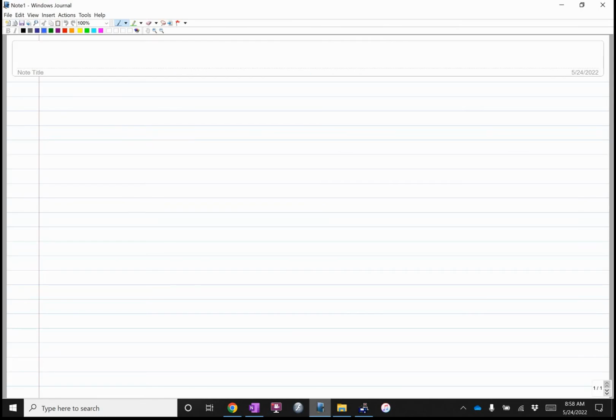So the amp hour unit, I'll come back to it in a second. It's really, really handy. I have a boat, and on there I have a battery that has 110 amp hours. Here's what that means. I can run a 1 amp appliance for how many hours? 110 hours before I need to recharge. I can run a 4 amp appliance for 110 divided by 4. It's a really quick way for you to figure out how long you can be off the grid before you need to go plug back in and start recharging your batteries.